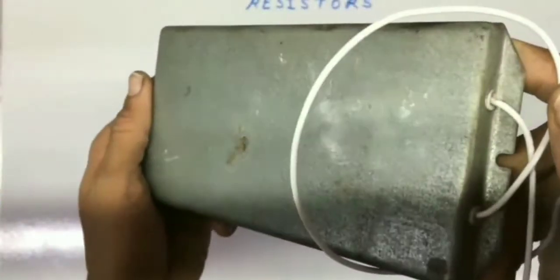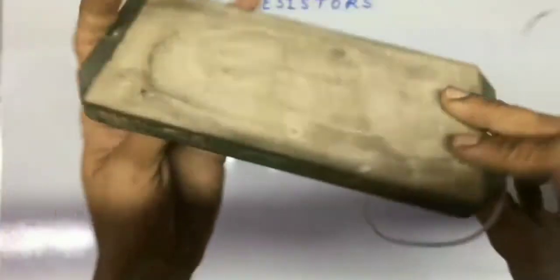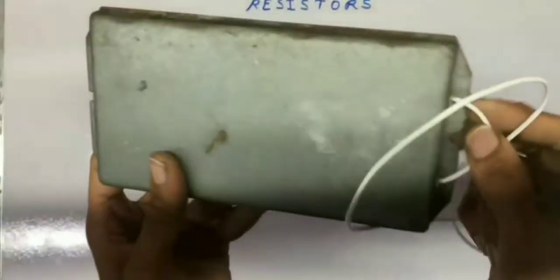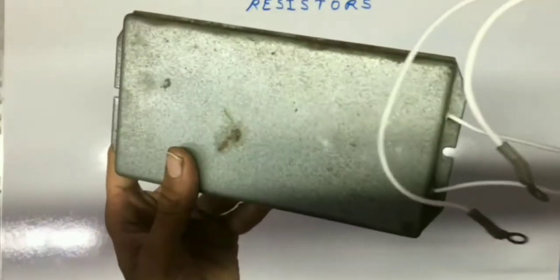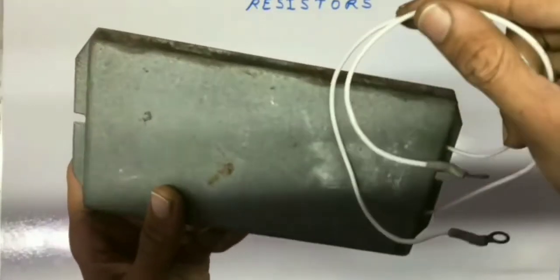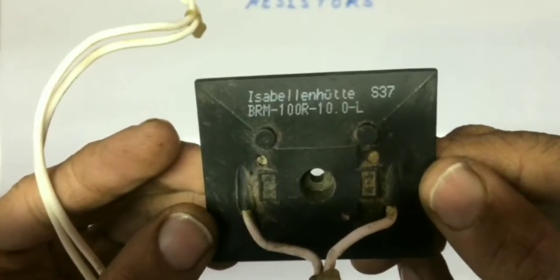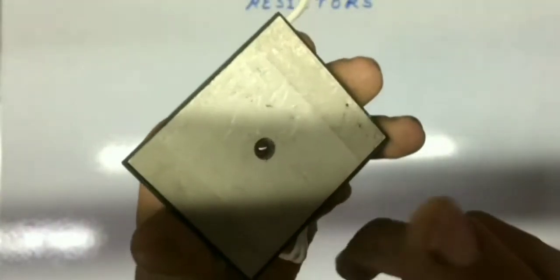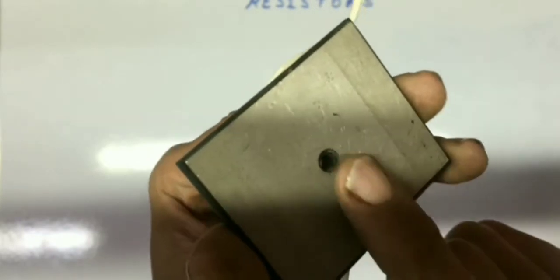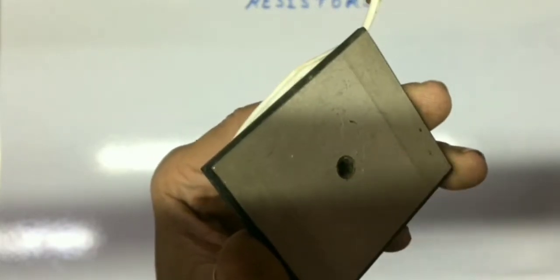And this is a metal clad resistor, 300 watt, 50 ohms. This is used in VFDs, in the pre-charge section, for soft starting of the capacitor bank. Small frame high voltage resistors, 100 ohms, 200 watt. These are heatsink mounted resistors. These need a heatsink to be mounted for heat transfer.